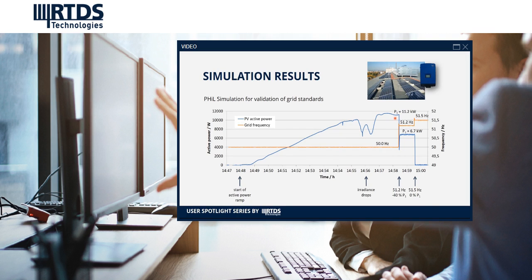Then I adjusted the grid frequency to 51.2 Hertz, which shall reduce power to 40% according to the standard. And indeed, we can see that the converter reduces its power to 6.2 kilowatt.